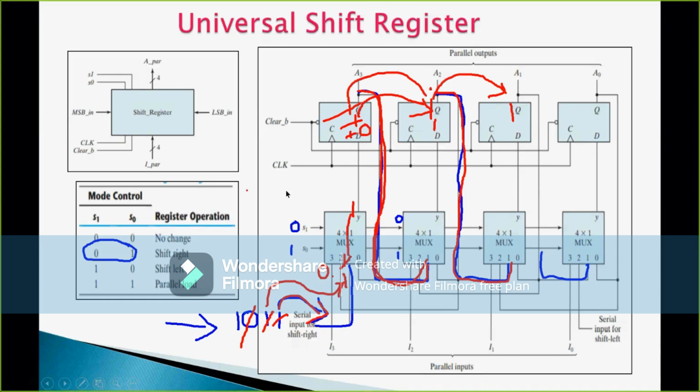Understood? So that time the previous elements everything will be shifted one position towards right. Now externally you are bringing in the next clock pulse. The fourth bit you are bringing now. When you are putting the fourth bit 1, what is happening? This 0 will be taken here and 0 will be given here. This 1 will be given here. This 1 will be passed towards this. That 1 is here now. So last 1 will be routed here now. See here the flip-flop contents now.